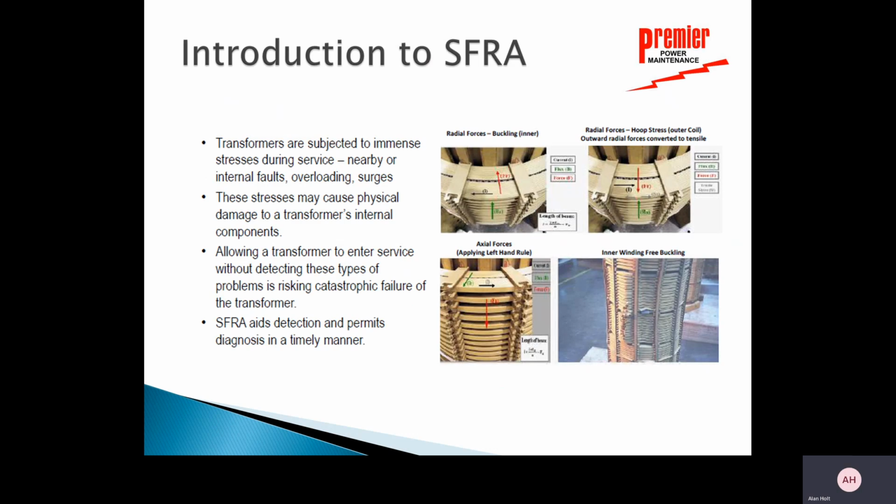Now, if we look at the actual transformer here, when you have faults, the stresses are just unbelievable. Faults, overloads, or surges, but faults especially. If I can see the forces here where the actual winding would go out or go in, that's called buckling. I can see axial forces here where windings would want to shift down or shift up. Here's a case where you can actually see some of those shifts right in through here. So those stresses can cause physical damage.